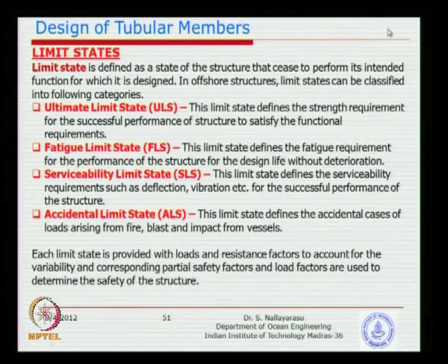So that is why you have several limit states. You have the ultimate limit state, which means it is going to collapse or fail by deformation. The limit state of fatigue, which we will look at in more detail in the next few classes, is basically failure by cyclic loads. Then the serviceability limit state is because of the deformation effects, like deflection. Vibration could also potentially cause a structure to be unable to serve the purpose for which it was built.